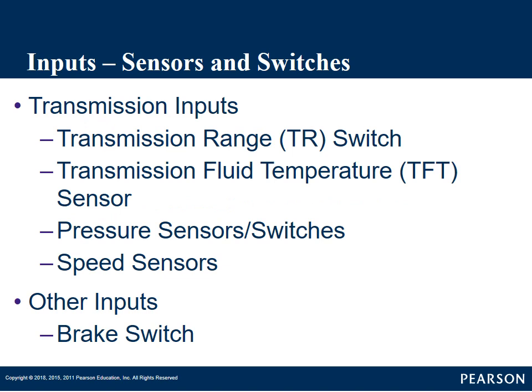Transmission inputs. Before I go much further on transmission inputs, and I'll say this again when we get into the diagnostics of it, before we make any diagnostics on the transmission, we need to be checking what's going on with the engine. Malfunctioning engine sensors or malfunctioning engine performance can cause shifting problems in the transmission. Always eliminate engine problems first before we deal with the transmission.